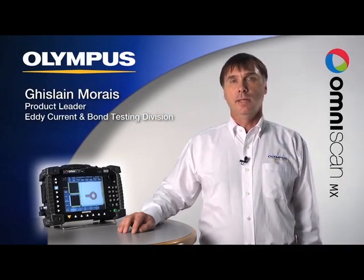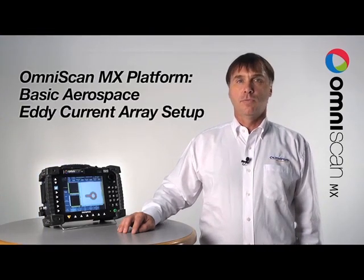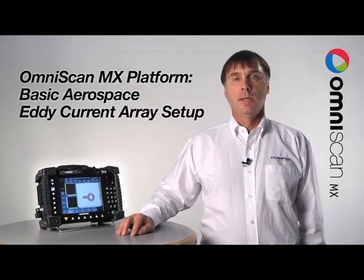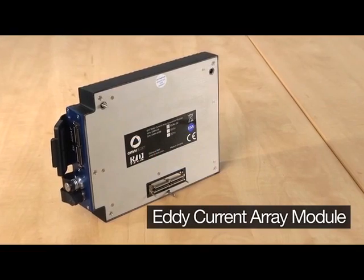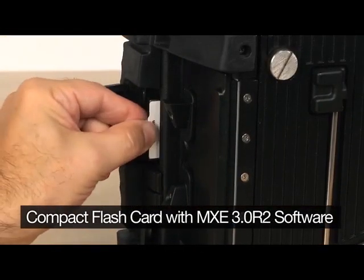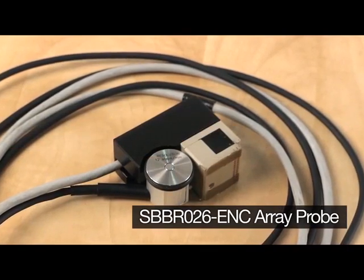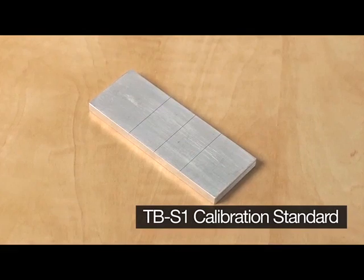Today, we will demonstrate how easy it is to perform a basic aerospace eddy current array setup in order to obtain a C-scan image. We will use an OmniScanMX, an eddy current array module, and a compact flashcard with the new 3.0 R2 software. For this demo, we will also use an SBBR026-ENC array probe and the TB-S1 calibration standard.